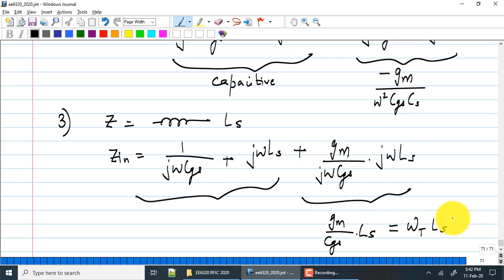Now this part is good because by adding a physical resistance, you are creating a resistive input impedance. That's the good part about this. It's a noiseless input match. That is the biggest advantage of doing matching in the common source amplifier using source degeneration with an inductance.